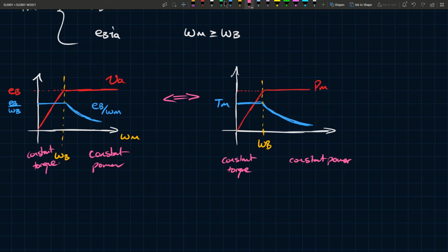Something else that you should also understand is that these kφ versus IF, or these magnetization curves, are usually determined experimentally, and they can be programmed into a lookup table and used for practical things. So if you're actually trying to build one of these things, you'll need some type of magnetization curve. In some cases, you can find the curves available online, maybe in data tables that you can program.